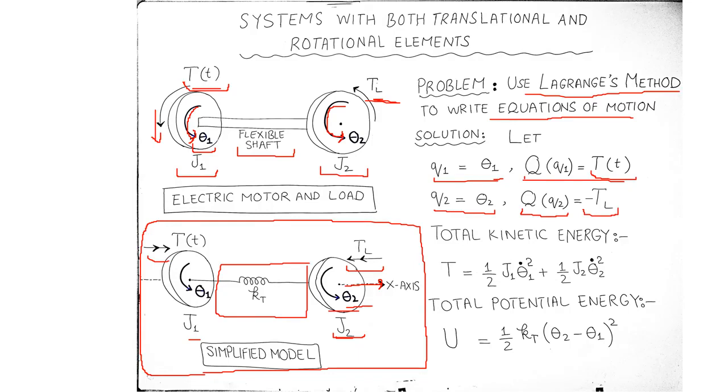This is very important. Note that when we define the displacement and loading pair, both should be in the same direction, or the loading should reinforce the displacement. In the second case, the loading is acting in the opposite direction to theta 2. In the first case, the loading is rotating the rotor in the same direction as that of its angular displacement variable, that is theta 1.